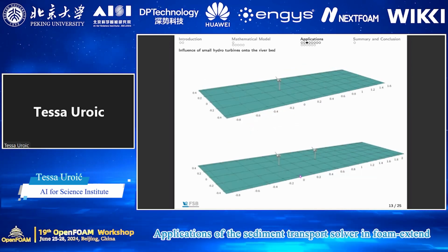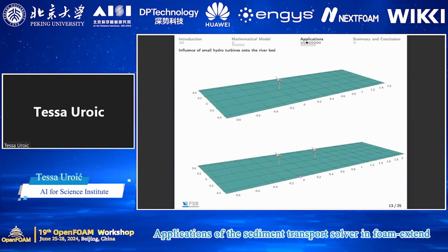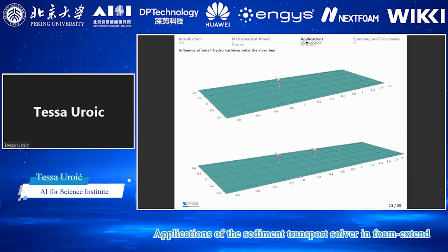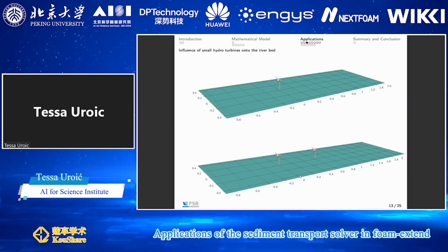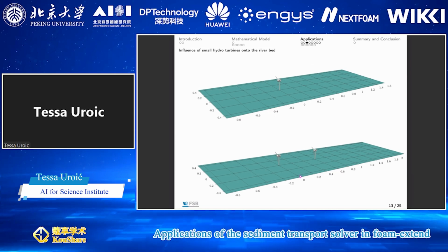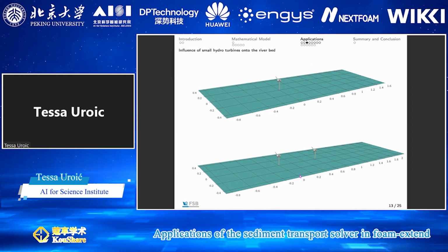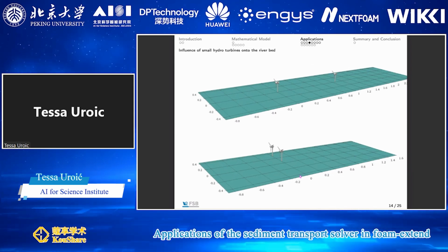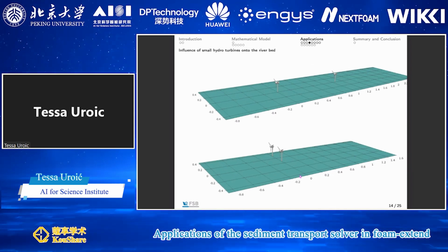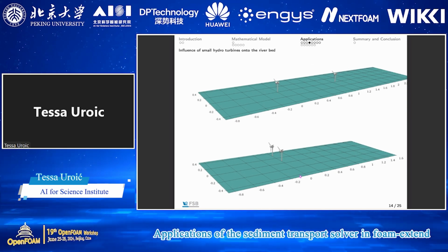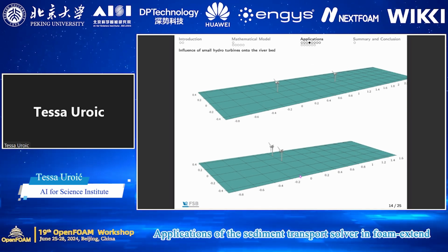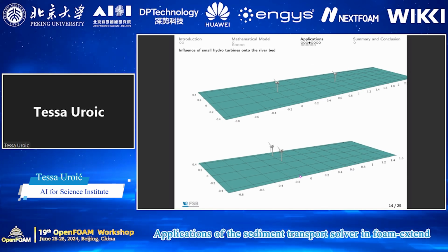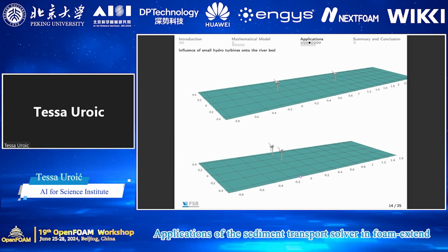And we have studied 4 configurations. First, we looked at a single turbine in the stream, then 2 turbines set one directly behind another, so coaxially. Then the same case with the 2 turbines one behind another, but with the distance between the turbines increased. And the fourth case was 2 turbines set next to one another, so radially.